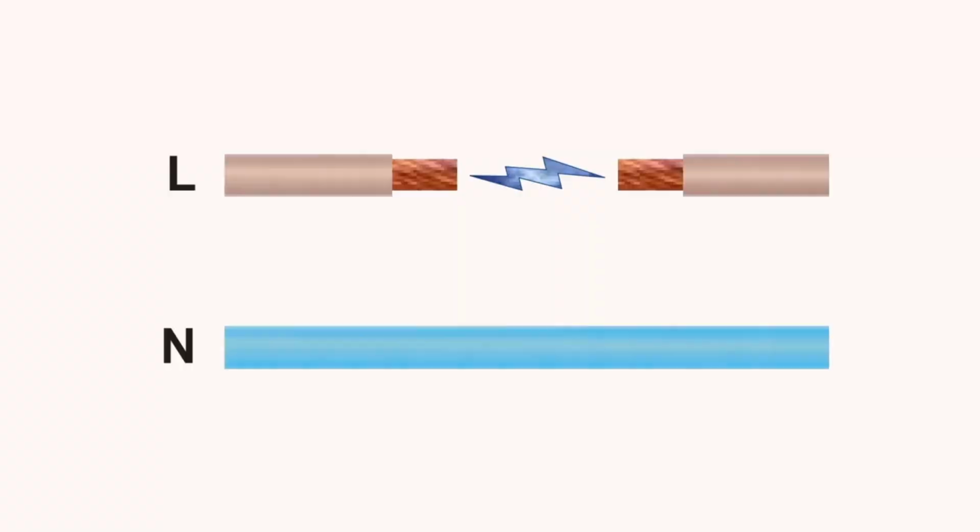We'll explain in a bit more detail how they work a little later, but let's stick with the subject of faults for now, as there are two different types of arc fault. These are series and parallel arc faults. The series arc is the one we've already discussed, where conductors don't make a brilliant connection with each other when they should. So let's say the line conductor in a circuit feeding an electric shower isn't brilliantly terminated into the isolator. The current may continue to pass through the connection and jump the small gap caused by the loose wire, then continue down the outgoing conductor to the load.